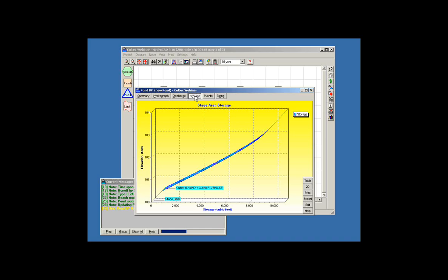Our next HydroCAD release, 9.2 next year, will actually handle this automatically in the wizard. If you do use the wizard for the V8, and you can do that, you just need to be aware that it is going to be calculating slightly greater length for the row of chambers because of this difference in the length of the start and end units. But you can still do that. And you could actually take a wizard model initially, and come back and modify that and fine-tune it later on in order to put in the start and end units.